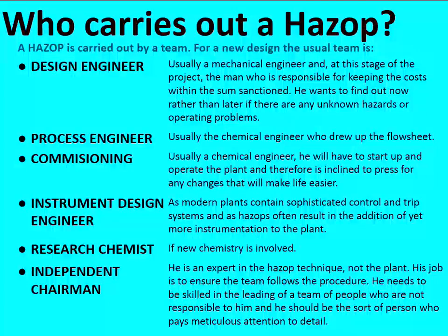And usually the independent chairman is from outside the organisation. Very experienced engineer, knows all about these sort of things, but isn't involved in this actual plant. And the reason for that is that if this lot, when they're doing the HAZOP, come up with a problem, and it turns out to be a really expensive problem, then the tendency is for them to go, we'll pretend that doesn't exist.